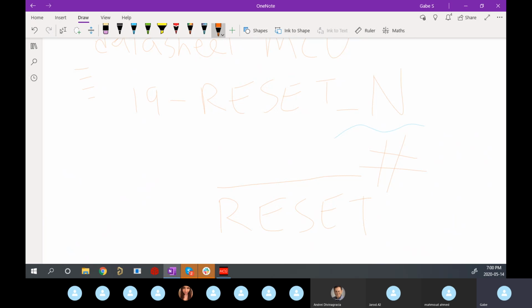If you're ever drawing a schematic, referencing a data sheet, or talking about an active low signal to someone, typing it out in this way is the most clear way to indicate what they should expect. If you say the reset pin went high, it sounds like it reset the microcontroller.